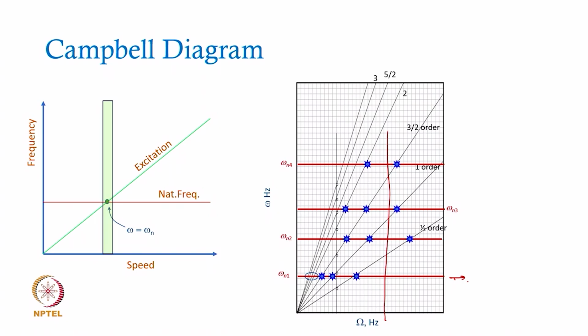Then what do you do? So, suppose you have decided to operate your engine at this particular speed, you already are staring at two possible resonances, all right. So, the job for you is to navigate the operating speed either here or there, right. What is the other alternative?